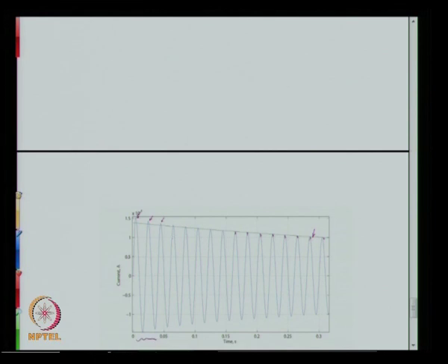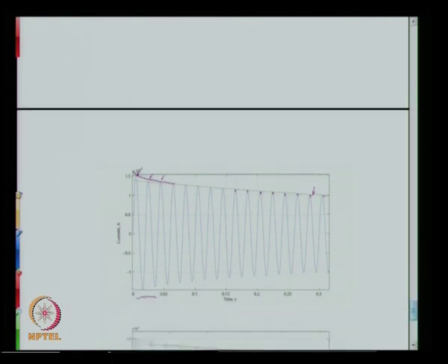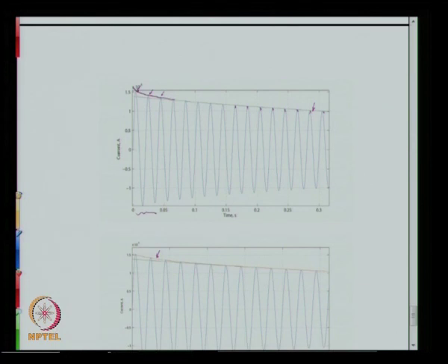The actual envelope joining all the maximum amplitudes of the sine wave should bend over a little more and go higher, and indeed if we add the other exponentially decaying term, that is with respect to T double dash d, then you see that is really what happens. This red line now shows the envelope after adding the T double dash d decaying term.